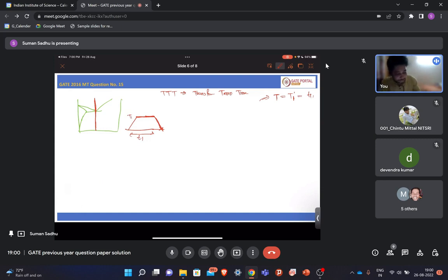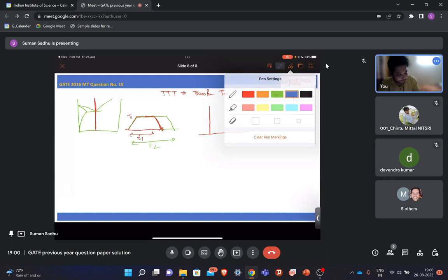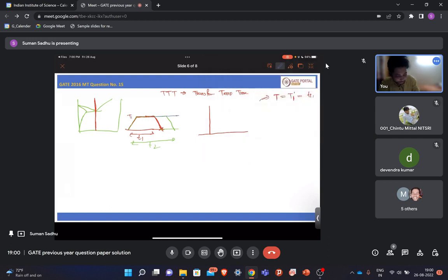So now, let's say you did this for a different set of times at the same temperature. This is one, then you hold it for T2 time, and again let's say you hold it for up to T3. So same alloy, we will do the isothermal annealing at a temperature for different time intervals.